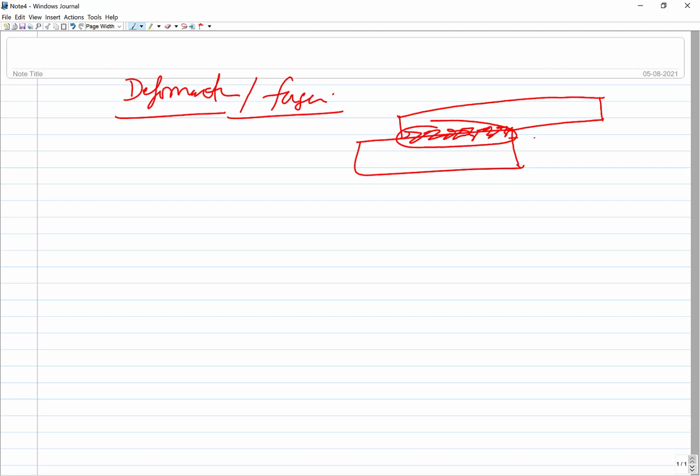This zone as a whole may be only 2 to 4 micrometers, but still the metallurgical continuity is developed. So diffusion coupled with very good micro level mechanical deformation at the interface leads to a good metallurgical joint. The joint strength may be even higher than that of the base metal. So the joint is very good in this case, except that you need proper cleaning so that no impurities and oxides are present at the surface.